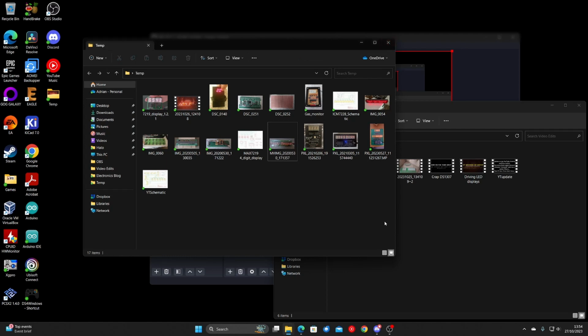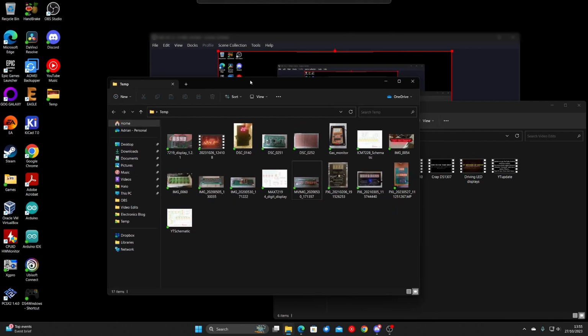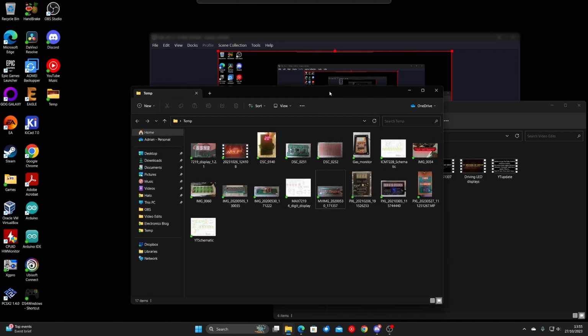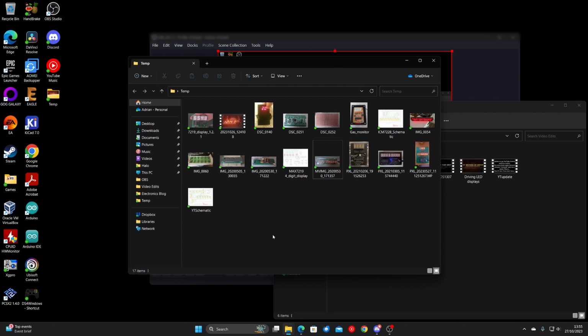I'll put the pros and cons in text form as I go through the video. I'll put a little description at the end where you can read an article on a blog about it. But basically, to sum up, don't believe everything you find on the internet, because a lot of the examples just won't work. You find many of the circuits have not actually been built; they're just done on a simulator. Like I say, the biggest thing is no current limit resistors for the LED segments when you're directly driving them from a microcontroller. That is absolutely important.